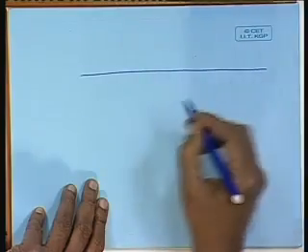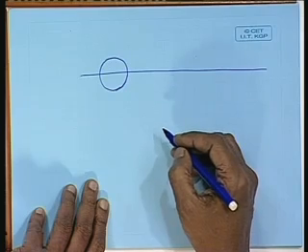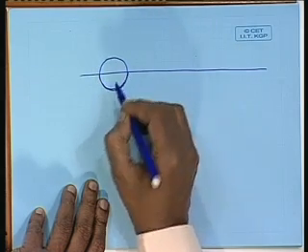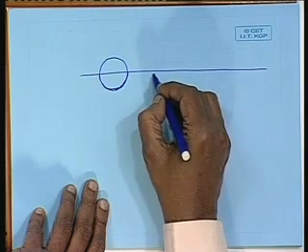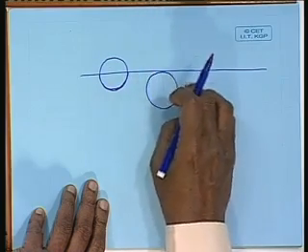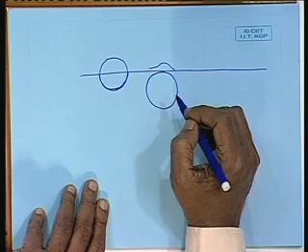So, the drag due to a submarine just below the surface will be more than drag due to a deeply submerged submarine, because just below the surface, say for example, this is the water surface and a submarine is here, you have the full frictional resistance due to the full surface, and also you have wave making resistance on top.